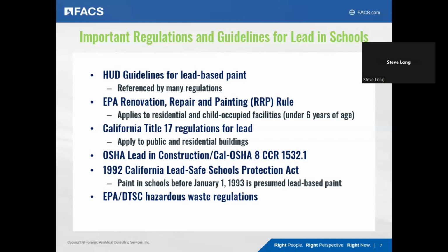And then finally, there is some hazardous waste implication potentially for lead, in that the levels of lead in paint can exceed the levels to classify it as hazardous waste. So if we're scraping paint, the waste created from that may well be a hazardous waste. So testing is important to determine that.